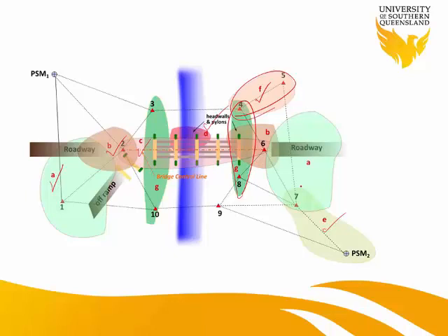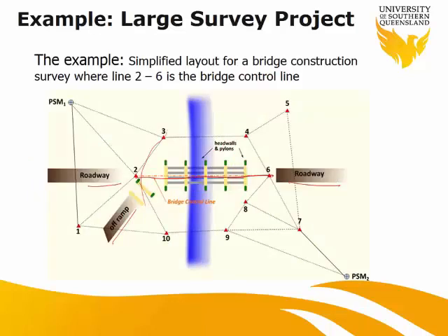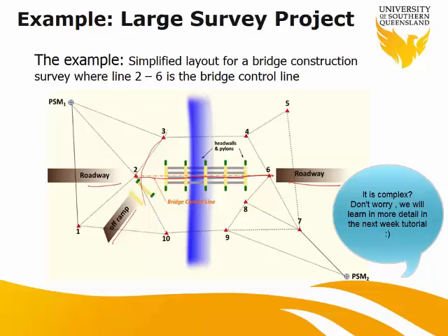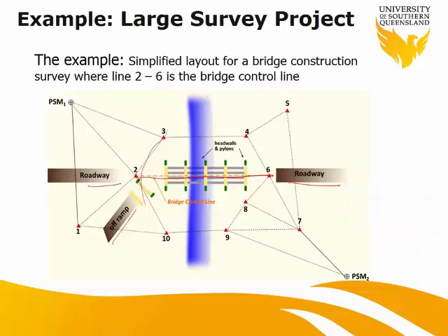Once you decide, you can just prepare the plan like this with rough positions of the points you want to set out. Obviously, you can also do the pre-survey and get some positions for them, and then come back to the office. You have to remember, planning should allow you to design a network like this, and then you might need to repeat it many times to get the ideal position for all those points, as well as the required accuracy that you need to achieve. You also need to think about the optimal location of secondary control and recovery stations, which you also need to assess.